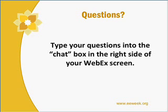So, that said, it's a little bit complicated, but in general, if you're talking about two local water supplies, a surface water source is generally going to be less energy-intensive. Another thing to complicate matters a little more is groundwater supplies can require less treatment, if it's a protected groundwater source. So, if you're getting surface water, say, from the Mississippi, where there are a number of upstream users putting contaminants in, it can require a lot of energy to treat contaminated surface water. And so, again, that complicates things a little bit, but in general, surface water sources are less energy intensive than groundwater.